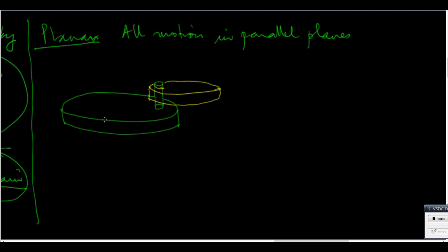So the motion of this one is in a horizontal plane, and the motion of this one is in a different horizontal plane, but the motions of this and this are in parallel planes. In this also there may be thickness, there are different particles, but each particle moves in a plane and all those planes are parallel. Then it is a planar link, but you need not have just a planar link, right? So for example, that robot I had drawn earlier is spatial.